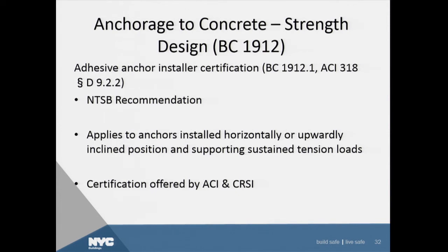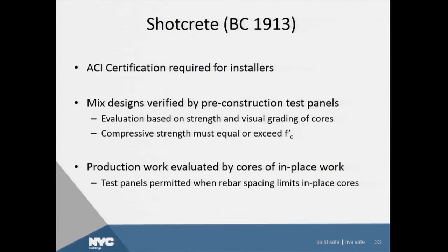Anchorage to concrete design based on ACI 318 Appendix D. One of the changes here is the installation of adhesive anchors in certain instances, basically from the horizontal position to the inclined vertical to completely vertical, has to be done by certified concrete installers. The ACI provides a certified installer program nationwide, and they go through this on a regular basis. The courses are available, but this is going to be required going forward as part of the 2014 code. I've been told here I need to speed up greatly, so I'm going to do that right now.